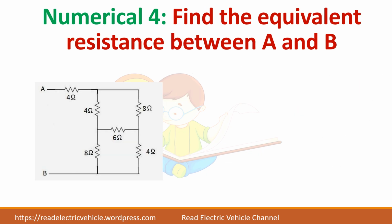Now see this problem where you have to find the resistance between the terminals A and B. So you see here it is not easy to reduce the resistance here. So what we can do is we have to apply some star delta transformation to reduce the circuit and find the equivalent resistance between these terminals A and B.